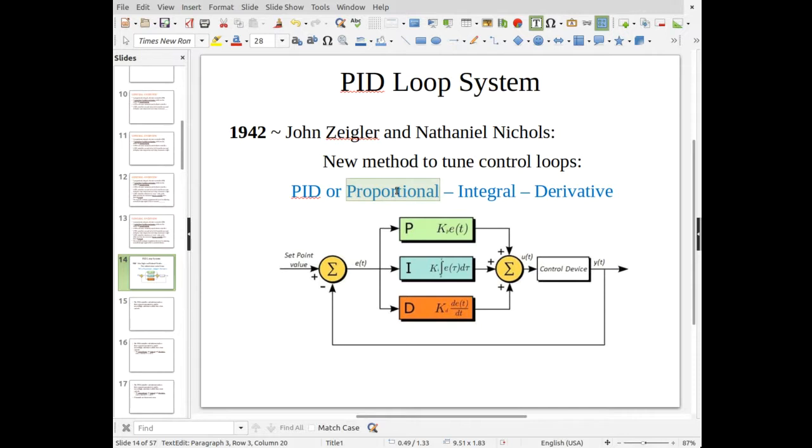You have this delay built into a PLC or any type of digital computer-based control. You've got this scan, so you've got to read in the data, run through the code, calculate your outputs, and then send those outputs out. So it's very slow.